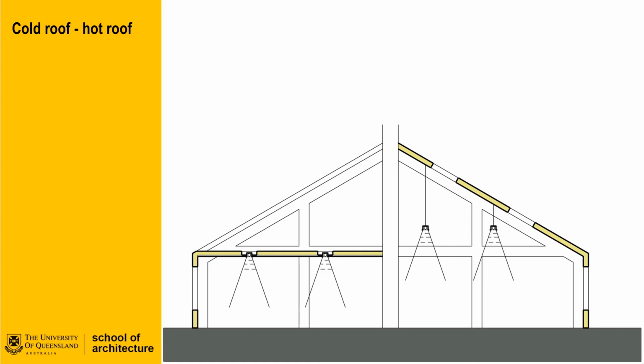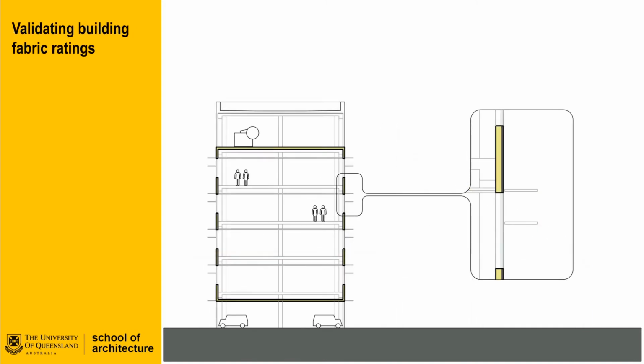These clearances break the integrity of the envelope, and the accumulative effect of these breakages are factored into the Section J calculations. Typically speaking, many facade contractors and manufacturers of certain building materials will provide data relating to the performance of wall assemblies. Manufacturers will usually also be willing to assist with a calculation of transmission values, such as the overall U value of a proposed wall assembly.